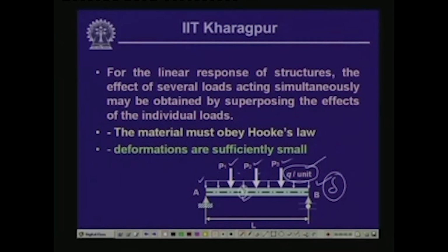It is expected that the results which we get in either case are identical. In the first case we use the differential equation for elastic curve for the whole lot of loading and compute the deflection, and in the second we employ method of superposition by using differential equation or area moment theorem, evaluate the deflection at that particular point for individual loading and sum them up.